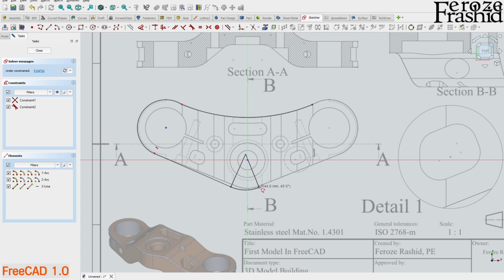There it is. So it switches through the different modes of polyline if you hit M on the keyboard. We want to draw another arc, and then by default, right after an arc, the straight line goes tangential to that arc. Somewhere at this point, left click, and then go to the end of the line, and then hit M, M, M until it gives us the mode that we want. Right there. So right click to exit out of that command, and we got our outline.